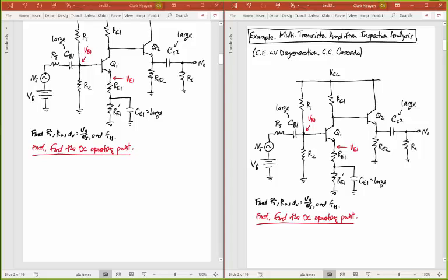And then you're going to have that voltage across these resistors, and a voltage across the resistor creates a current that then gives you the current going through this circuit. So in the end, it's the voltage across the REs down here that gives me the current. And in the end, that's going to give me what I want out of this, which is basically IC1. I want that DC bias current going through that. So let's go ahead and do this.